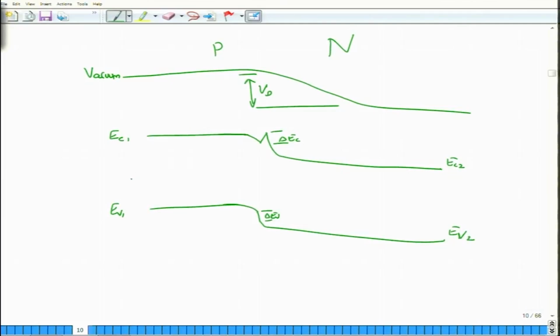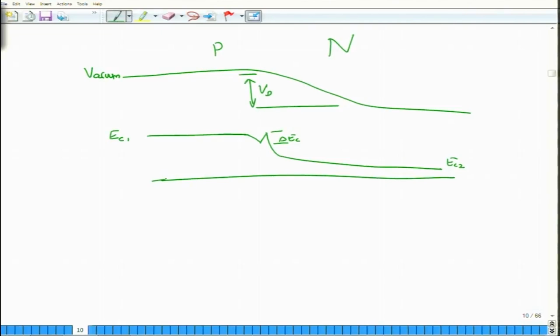Again, in the equilibrium position, let me move it, because in the equilibrium position the Fermi level has to be closer to N, but it has to be closer to this material also, right. So, you will actually have EV1 here. So, this is the Fermi level, which is constant under equilibrium, drops down, there is a sudden drop of delta EV and then drops down to EV2 here. Okay. So, this is what the band diagram of a small p and a capital N region would look like.